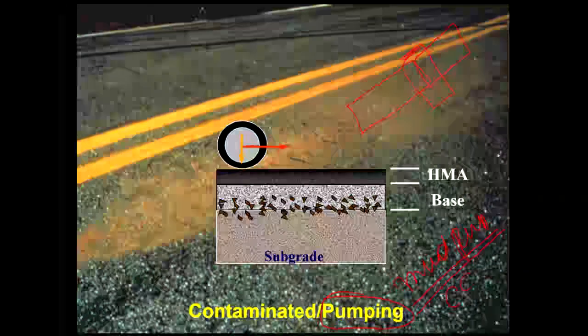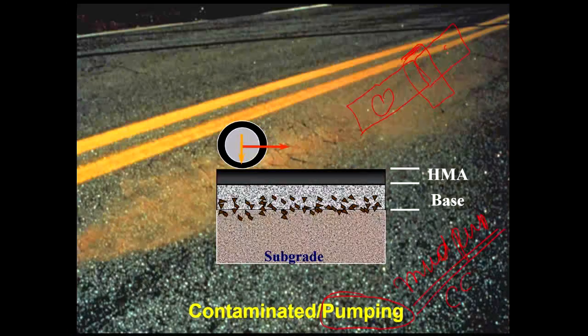So this is one slab, this is the second slab, and this is the joint. Because of the movement of the traffic over a period of time, the joints get deteriorated. Thereafter, there is an elevation difference. Because of the elevation difference, it comes like this, and it also comes something like this. So this is the source of the water.